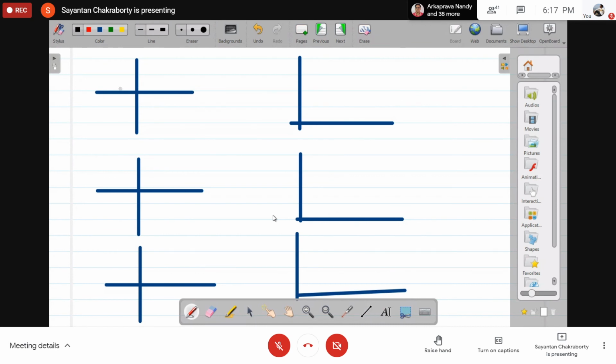Okay, if the pole is in the left half, you leave it with an initial condition and it decays down. But if the pole is in the right half, leave its initial condition, it will grow exponentially, right? So this is one case. If you have complex conjugate poles like this, then what you will have, I think the mistake is over here. So this line should be drawn.